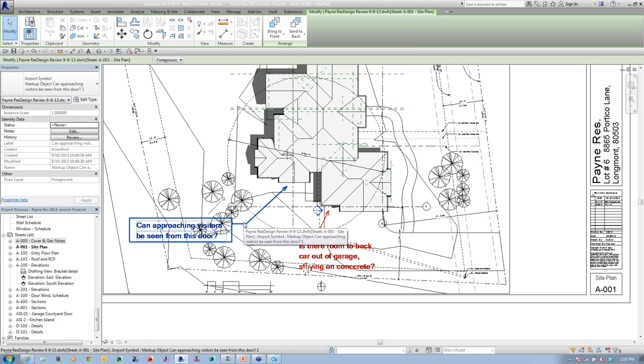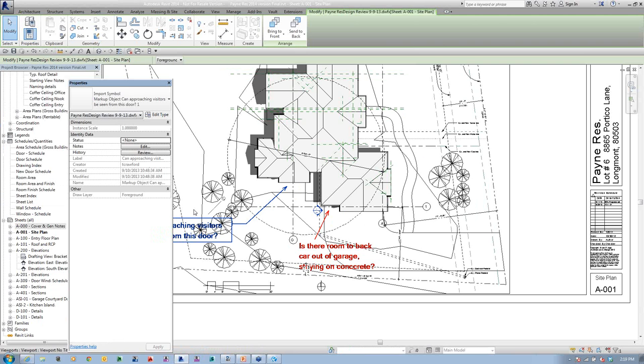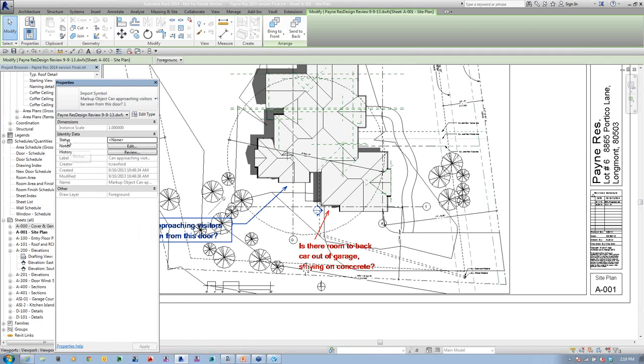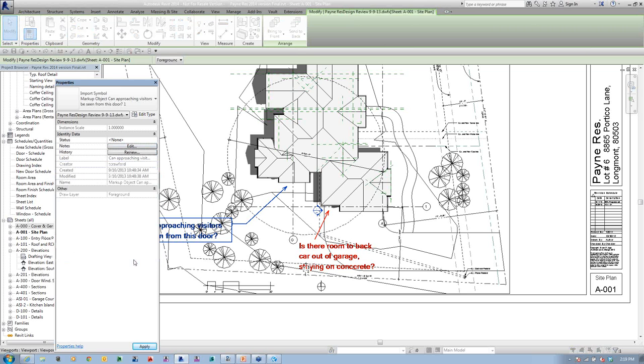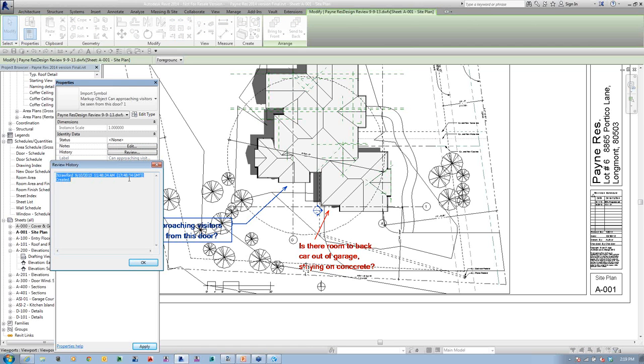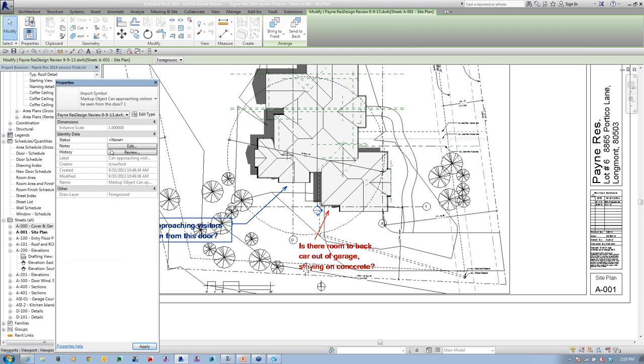With the markups in Revit, I can select it and see the information about that markup. I've got the status in here; it's a question for review. I've completed it inside. We've got the different notes that we can list with it, and we can go in and select the review history on here. We can see this is from T. Crawford. That's Tony doing this, and then we've got all the different things inside here, unless these are blocked out at the moment for us. Bring to front, send to back. So if you have multiple layers, you can layer those notes on top of each other and change what's inside.